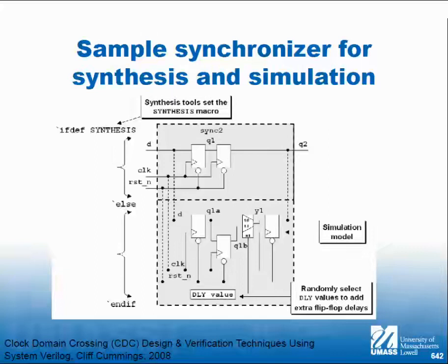An important thing, sometimes in simulation, you have a different model that you're using than what you synthesize. That can help you simulate other parts of the design, but ultimately you always need to simulate what you're synthesizing. That's what this ifdef does. So this is what you're synthesizing. This is what you're simulating. Ultimately, you always have to do this, but this one you can muck around with delays and how things are going to try to force metastable states. Just think of what it would take to do this to 200 signals, for example.